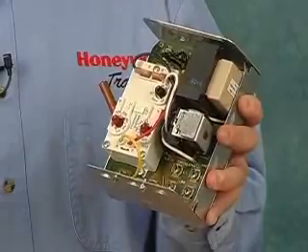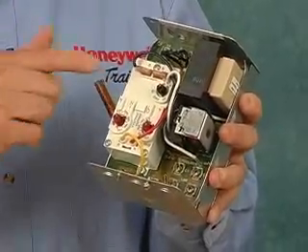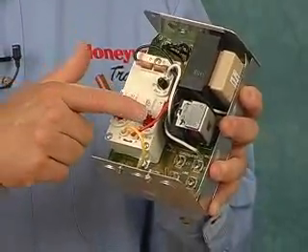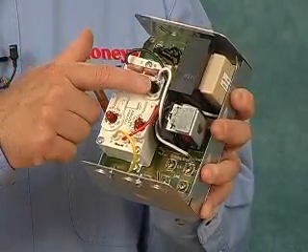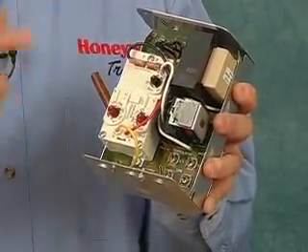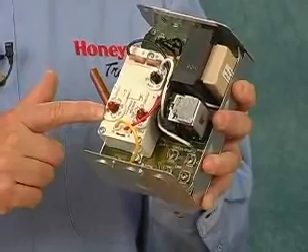What's different is that the aquastat has got a couple more dials. One sets the low limit and the other sets the low limit differential. The high limit differential is fixed at 10 degrees. When the boiler water temperature gets below the low limit setting, the burner is brought on so the boiler stays hot enough to supply domestic hot water. At the same time, the circulator is prevented from running, so if necessary, the entire output of the boiler can go to making domestic hot water.